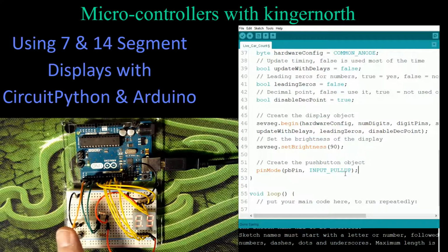There's power on this coming from the board all the time. And there's an internal resistor for that pull-up resistor. It's internal to the Arduino Uno. So this just makes it simple to connect. So when I press it, I actually get a ground or 0 volts. When I'm not pressing it, I get 5 volts on the input pin. Simple as that. That's what we're doing. That's what we're looking at. So that's what all of that's about. We'll add the other stuff later.